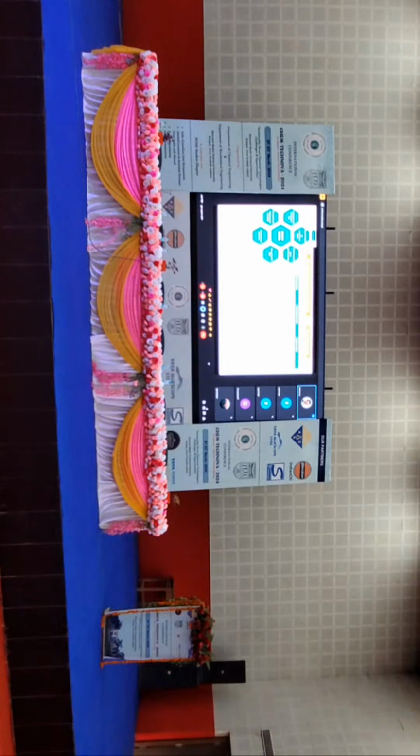So if you see your electric meter, how much load have you taken? You must have taken 5 kilowatt load, or maybe 7 or 8 kilowatt, up to 10 kilowatt, not more than that. But if you want your vehicle to be charged within 2 minutes, you need 1.5 megawatt of power. If you want your vehicle to charge in 15 minutes, then the same calculation, 50 kilowatt hour divided by 15 by 60, you will see it is 200 kilowatt or 0.2 megawatt.